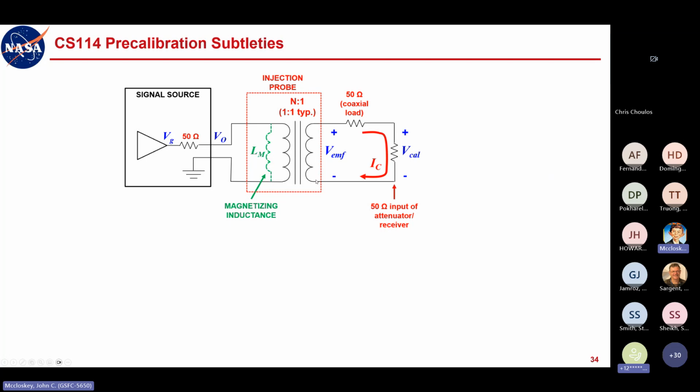Now in this case, while you're still in the calibration fixture, it's the center conductor of the calibration fixture going through the pair of 50 ohm resistors. So I've just shown those in series here. You have the 50 ohm dummy load up here, and then your calibration potential is what your measurement device is reading across its 50 ohm input impedance.